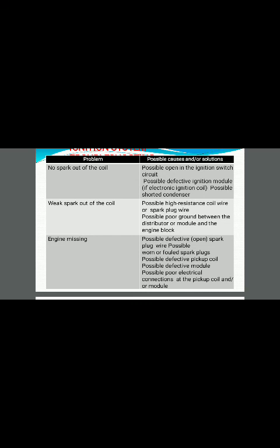The second solution may be a defective ignition module. A defective ignition module means there may be some component in your ignition system that is not functioning properly. If you are using the electronic ignition system, it may also be a shorted condenser.